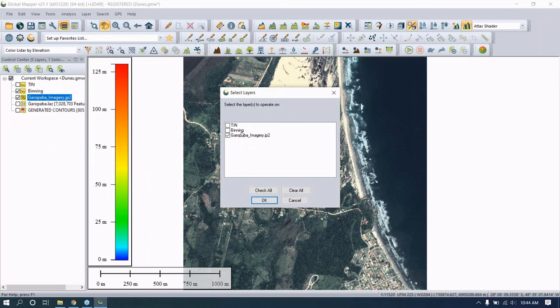And you would create that using these layers. We'd click OK. This does take a little bit to construct that mesh, so I won't execute that here, but it will create a mesh layer that you could then export to an OBJ or another supported mesh format. Perfect. And to clarify, the option in the LiDAR module toolbar is obviously directly from the point cloud. So going from your binned model using that method from the analysis menu works.